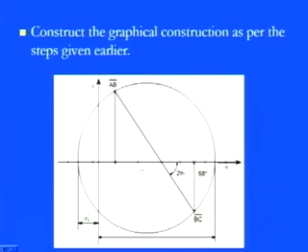Then this is my center point, we can also get the center point coordinates. This is my diameter. So through this, if you know the 2 theta, then we simply rotate this by 2 theta, get this AB bar to BC bar as a diameter, and then once you have these things we can simply get the radius. Or by simply taking the intercepts from these two, AB or BC, on the x axis, we have the tau xy. So this tau xy is there, and the sigma 1, sigma 2 we can simply get from the sigma x and sigma y.